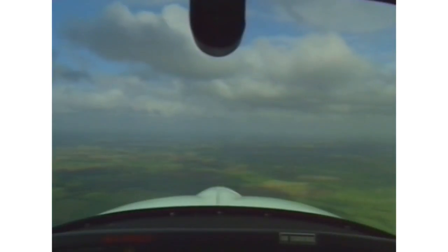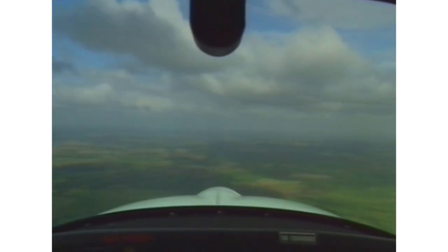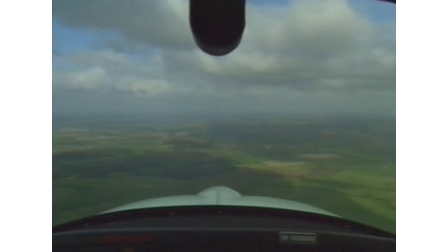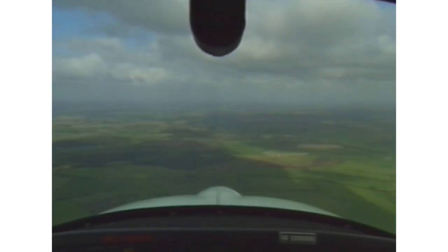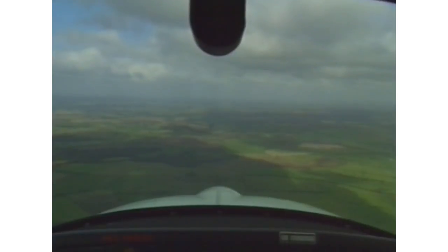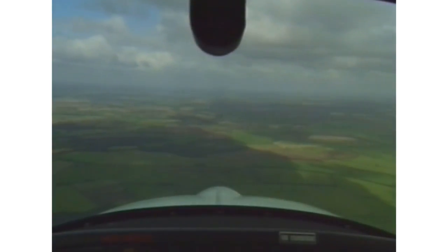Alright, very quickly I'm putting the aircraft back into the glide descent, good lookout beforehand, 80 knots. Let's now look at the effects of flap. I'm now selecting flap down to 20 degrees. To maintain the speed with the increased drag, I'm having to select a lower nose attitude. Airspeed being controlled by attitude, but rate of descent now has been significantly affected by the flaps.